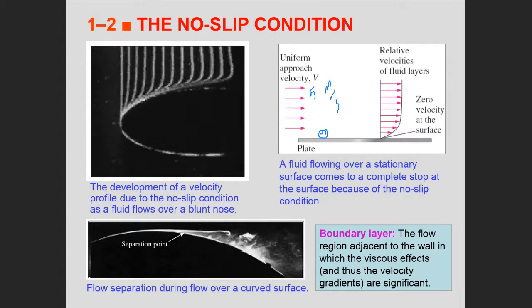He is absolutely right, because the plate is not moving. Any molecule in touch with the plate will have a 0 velocity as far as the plate is stationary. And that is what is called, ya shabab, no-slip. Non-slip means what? Slip means able to move. Non-slip means unable to move. Any molecule, gentlemen, in touch with a stationary solid surface, the velocity is what, guys? It is 0.